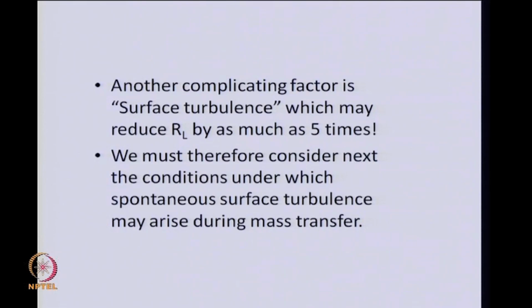If there is a flow in the surface, then by virtue of the finite viscosity of liquid, the liquid underneath will be dragged. So, because of presence of non-uniform surface concentration, there can be unsteady movement in the surface leading to mixing in the subjacent liquid layers, and therefore, it can have a compound effect on mass transfer.